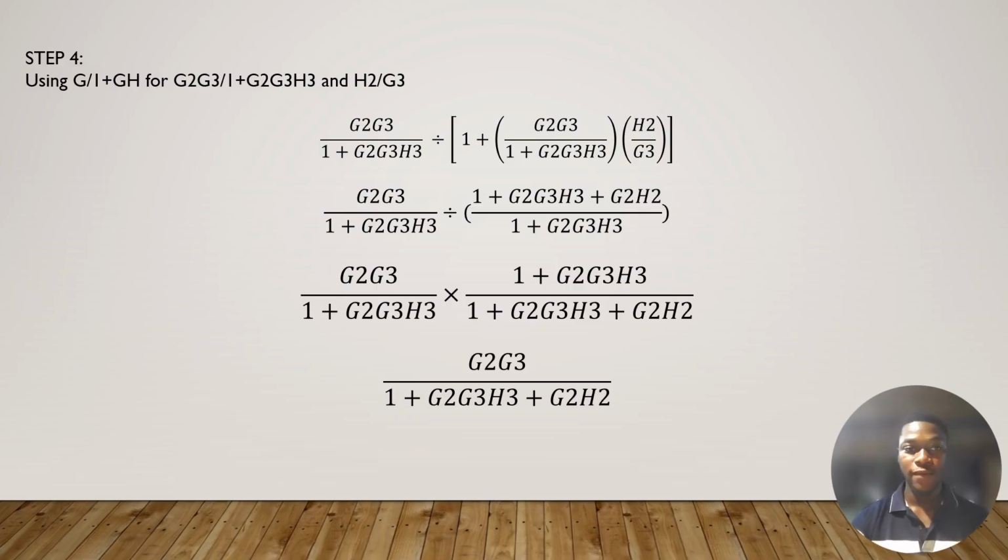We also observe that H2 forms another feedback loop around parts of the system. By applying the same reduction principles again, we continue simplifying step by step until the diagram is reduced to a single forward path with a single feedback expression. This systematic approach ensures that we do not miss any connections and that the final result is mathematically correct.